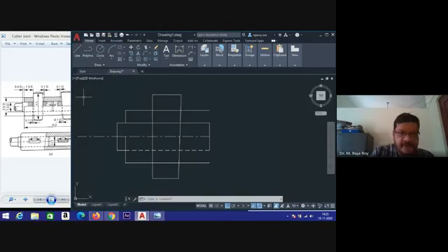For drawing these two arcs, you can use the 3-point arc. So here in arc, 3-point arc is there. So before going to 3-point arc, you just draw a small line like this here and here. At the midpoints, you can draw small lines. Then go to 3-point arc.